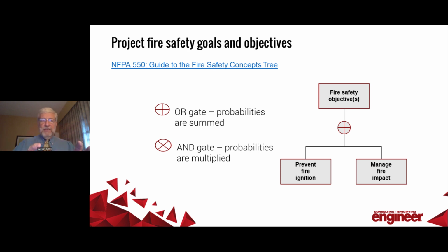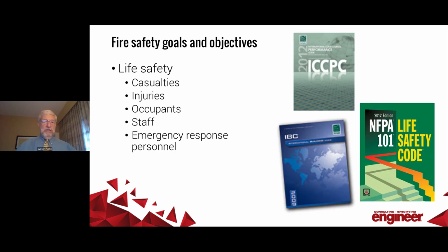So that's NFPA 550. I've also used this not just in design, I've used it post-incident to look at what really went wrong and what were some of the more significant factors with respect to the loss that occurred. So I'm going to go back and revisit Dave's presentation in terms of goals.